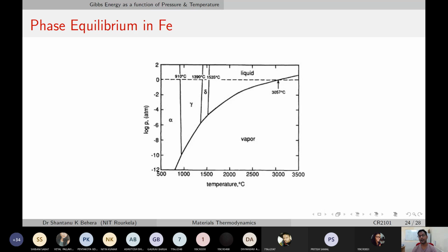since in the middle of the face there is 1 atom which is shared by the 2 unit cells, you'll have to take half of it. That means when you have 6 faces, you take 6 halves. That makes 3 full atoms. So you have 3 atoms from the 6 faces and 1 atom from the 8 corners. That makes it 4 atoms per unit cell.